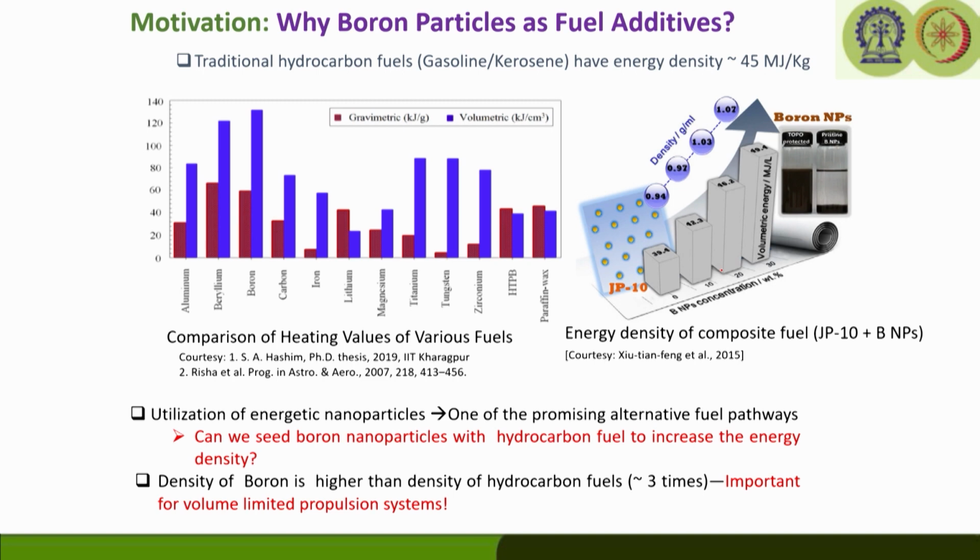Because of that, it is not yet utilized in practical combustion systems, but the promise is that if we can utilize the boron particles, it is going to be one of the promising alternative fuel pathways. You see it is written here also: can we seed boron nanoparticles with hydrocarbon fuel to increase the energy density? Now, the density of boron is higher than the density of hydrocarbon fuels, almost 3 times, which is also important for volume limited propulsion systems.